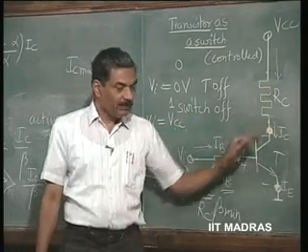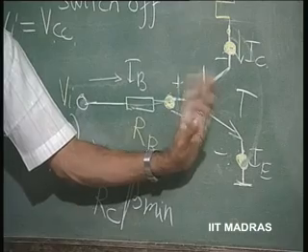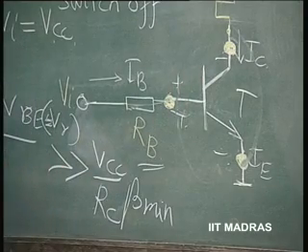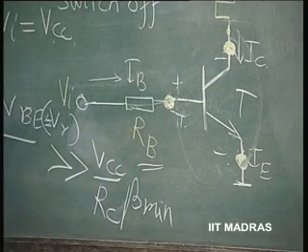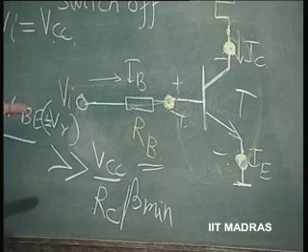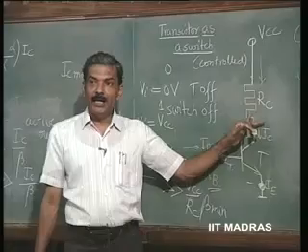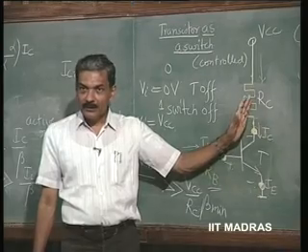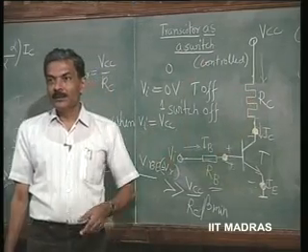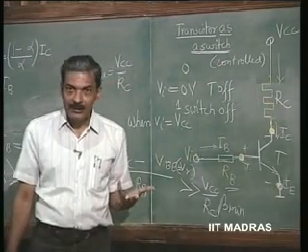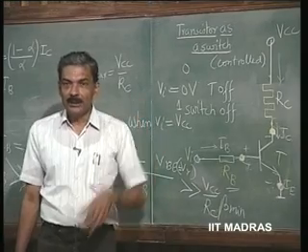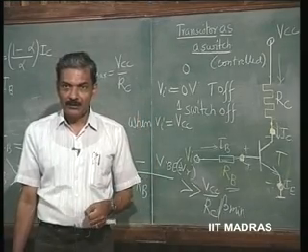So, any resistance within that range must be put here, okay, in order to design it as a switch. This may be therefore called a power switch. This transistor may be capable of taking currents of the order of amperes, and still act as a switch. This may be a relay coil, which may take hundreds of milliamperes maybe to sustain some switching action, right.